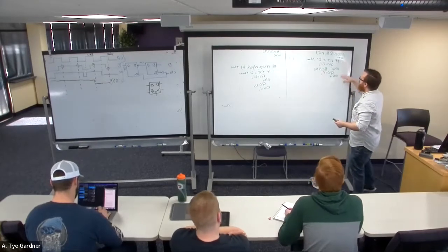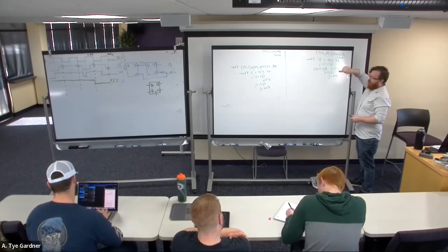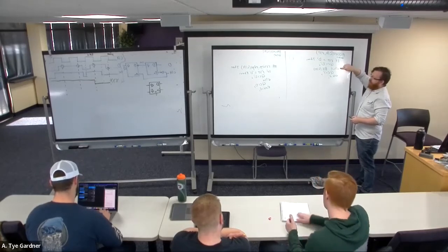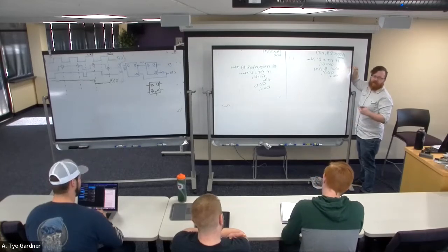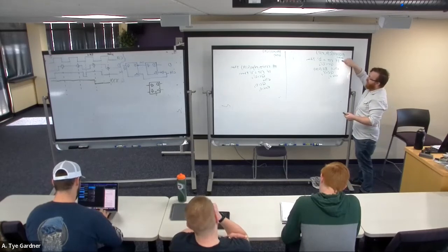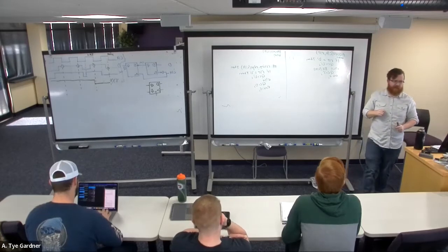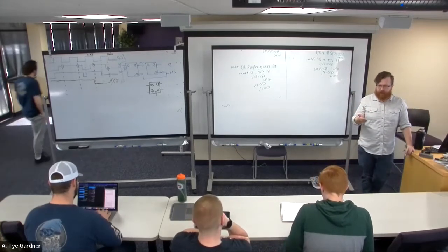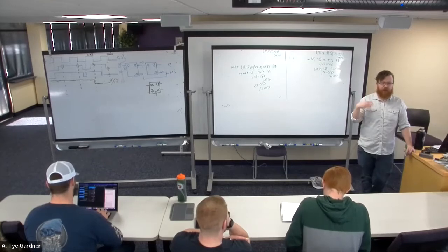But here, if I said, if rising edge of clock, then Q equals 1, else if reset equals 0, Q equals 0, that actually causes a problem because that's saying that the rising edge of clock would happen and evaluate Q and skip over the reset. Whichever if statement comes first, executes first. And if it sees the first one, it will just do that.